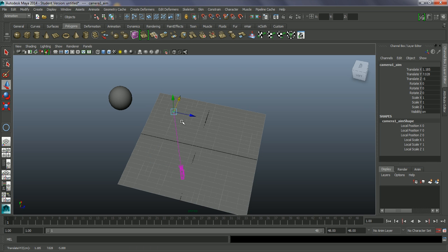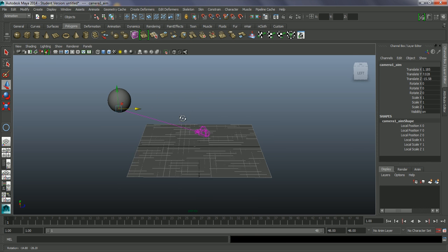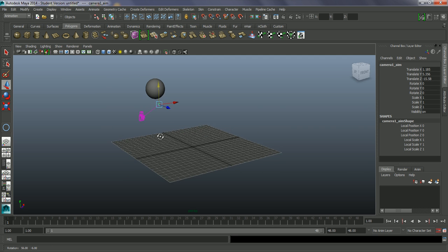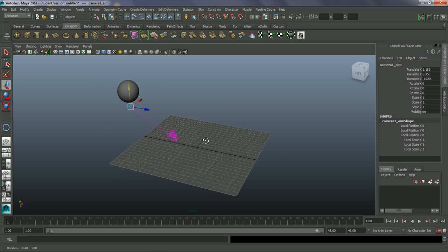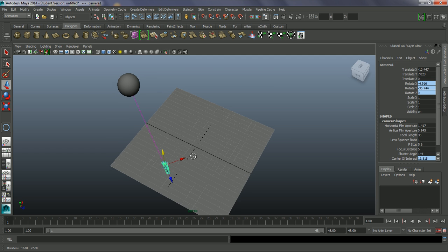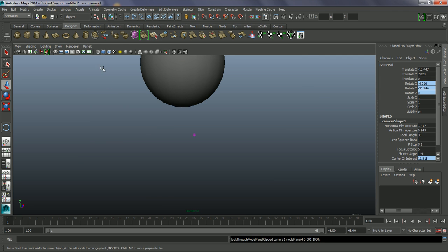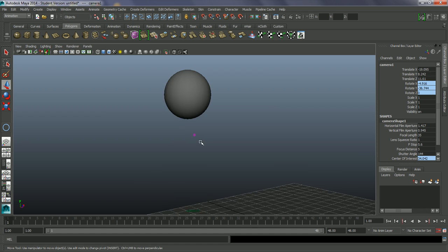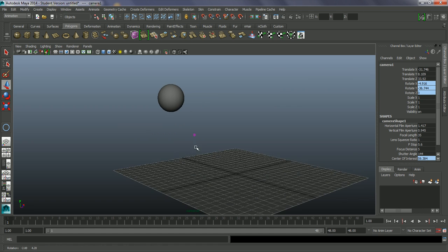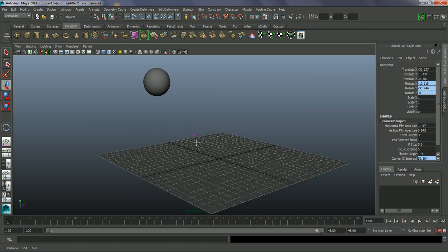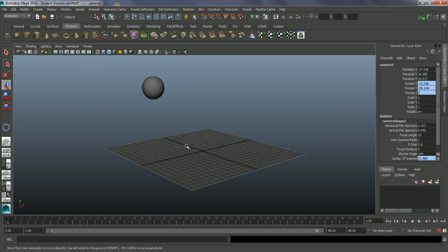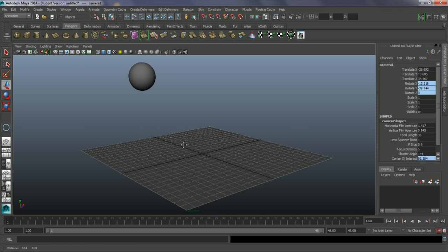So what I'm going to do is bring this aim just over to our object, maybe kind of down in the center. I don't really want this camera to go up and down. And then I'm going to click on the camera, and a useful thing we can do in Maya is go to panels, look through selected. We can actually use our normal viewport controls to position this camera essentially where we want it.